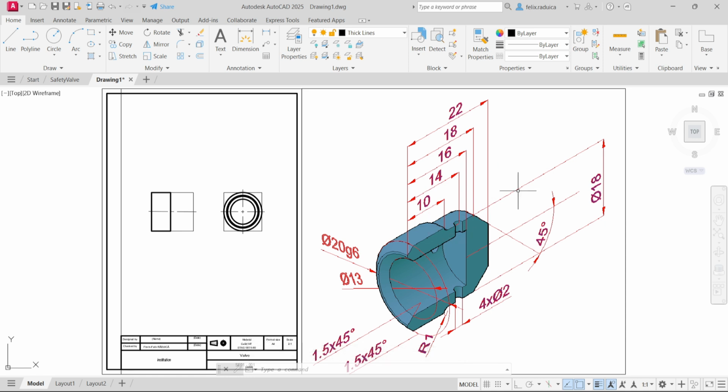After that, the next 12 millimeters should be of a diameter 18, but it is inside, so 9 against the axis line, 9 towards the top and 9 towards the bottom.